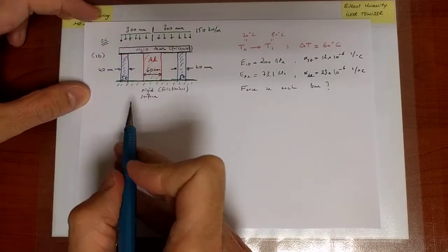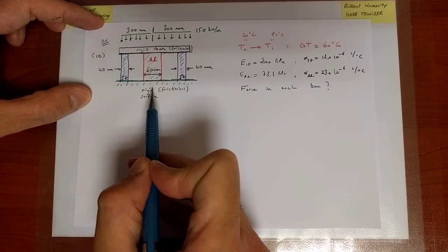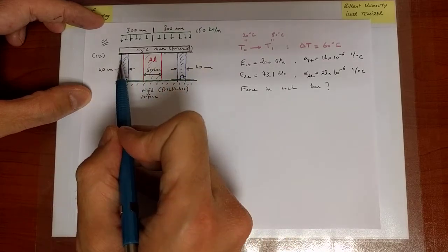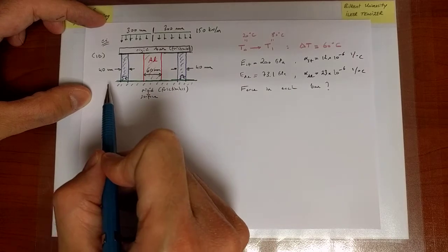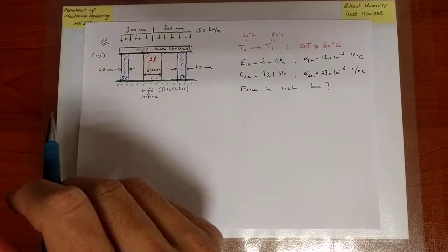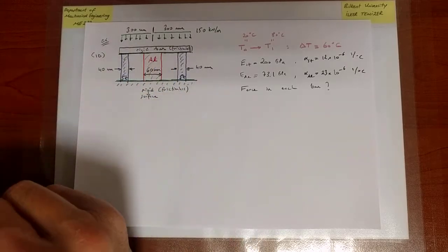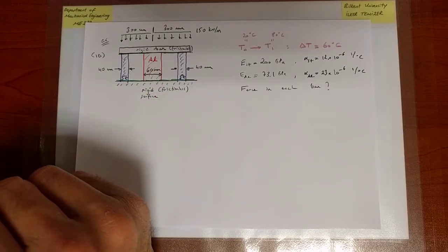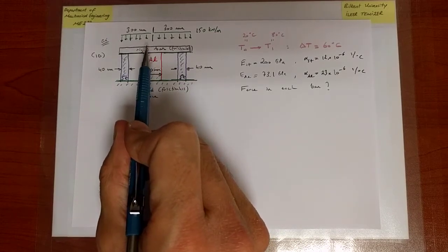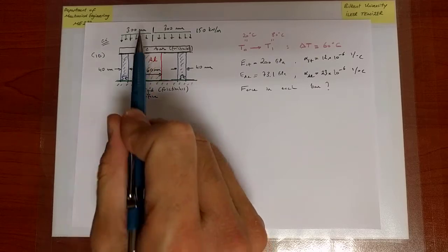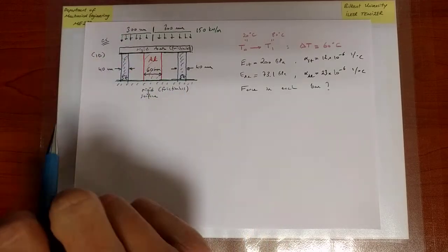And therefore, equilibrium requires that the sum of the forces along that direction is equal to 0. The moment about any point within the plane is automatically 0 because, again, these forces will always be the same. And due to the symmetry of the distances, 300, 300, the moment equilibrium is automatically satisfied. So the only equilibrium equation I have is that the sum of the forces along the axis of the cylinders is 0, but I have two forces: one equation, two unknowns.